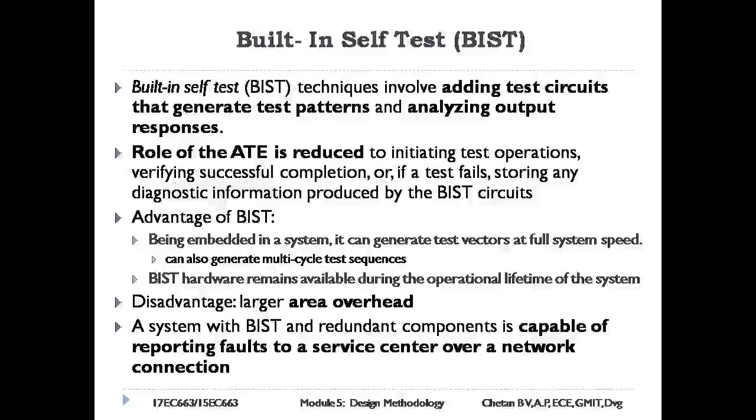Advantages of BIST: being embedded in a system, it can generate test vectors at the full speed of the system. It can also generate multi-cycle test sequences. BIST hardware remains available during the operational time of the system. The disadvantage is larger area overhead. A system with BIST and redundant components is capable of reporting faults to a service center over a network connection.